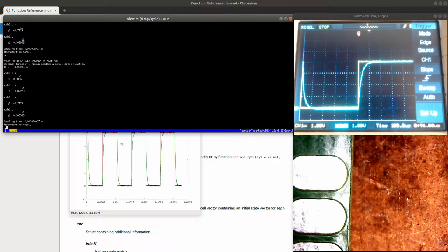So the Y is the signal that we plotted in the green line there, right? This model describes the full dynamics of the system given the input signal, which is U, U1 here. If we drive this dynamic model with the signal U, we get the response that looks like this, which follows very closely the measured data.